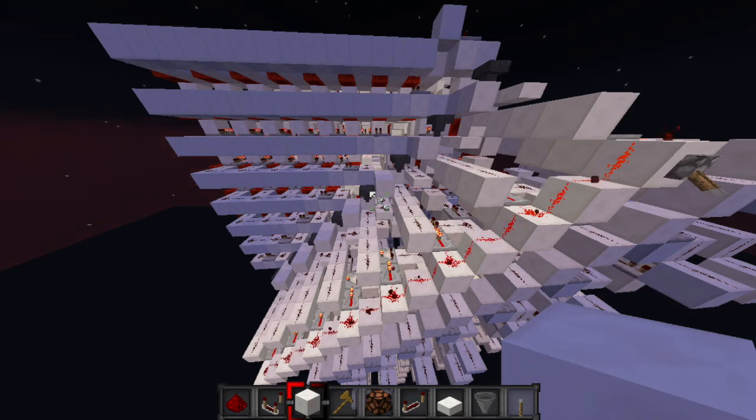What we're eventually going to be doing is transferring binary bits to our screen. That means we're going to select some part of the screen and send an 8-bit number to that part of the screen, and that 8-bit number is going to set the state of each of those pixels.